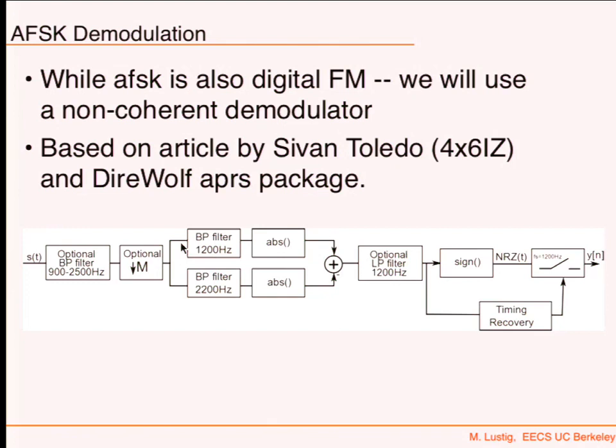This is, you get your NRZ signal, effectively. I call it analog NRZ because it's not going to be plus minus 1. It's going to be varying because of noise, but it's going to be positive and negative. If you would take the signum of it, the sign of it, then it would be really a pure NRZ. Okay? So this is what you have here.